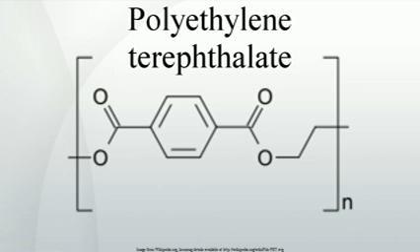Chemical recycling of PET will become cost-efficient only applying high-capacity recycling lines of more than 50,000 tons a year. Such lines could only be seen, if at all, within the production sites of very large polyester producers. Several attempts of industrial magnitude to establish such chemical recycling plants have been made in the past but without resounding success. Even the promising chemical recycling in Japan has not become an industrial breakthrough so far.